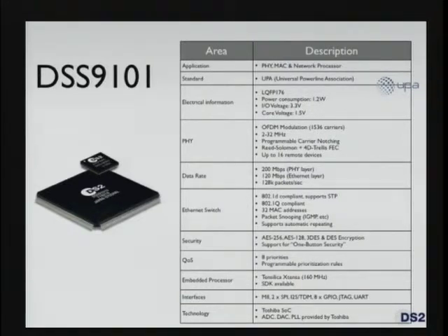runs on the processor. The interfaces of the chip are one MII interface, 2 SPI. Well, you can see all the options here. And it's based on a system-on-chip technology from Toshiba. And the chip has been designed by DS2, except for the converters and the PLL, which were provided by Toshiba. By the way, the converters are inside the digital chip, as opposed to having them in the analog front end, which is the other typical partition done in the industry.